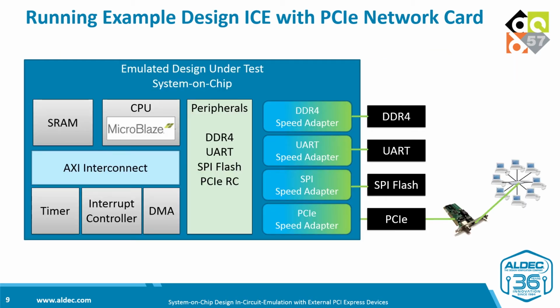The emulated design connects through the PCI Express speed adapter to the network interface card and then to the local area network. But every design provides several status registers, and often this kind of information is drawn to the I/O and connected to LEDs on the board. In emulation, however, there is a more flexible and powerful way to get status data. You can use a host workstation and a co-emulation channel, which in case of Aldec HES-DVM is SceMi link.